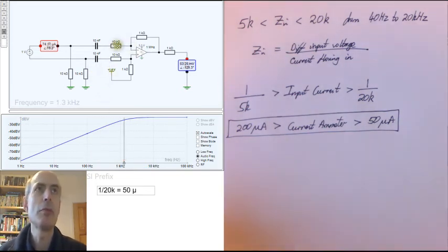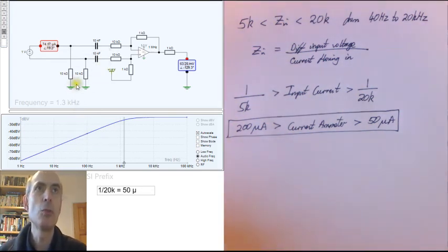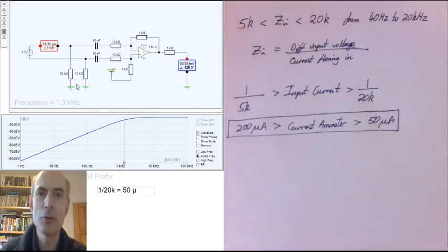However, you will notice that we've now changed the gain of our front stage here. The gain is now 1/10. 1k over 10k, so that's not a very good way to start your differential amplifier. You'll need a much larger gain than that. You can also see that we're nowhere near meeting the frequency response that we might want from an audio amplifier as well. We would want the audio amplifier's gain to be flat over the audio frequencies, and this one isn't. But that is a matter for another consideration. Just setting the input impedance, yes, this design would just about meet the requirements on the input impedance.